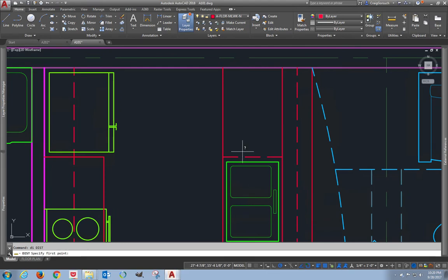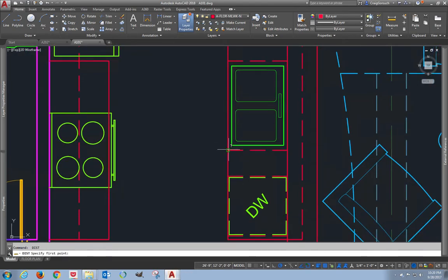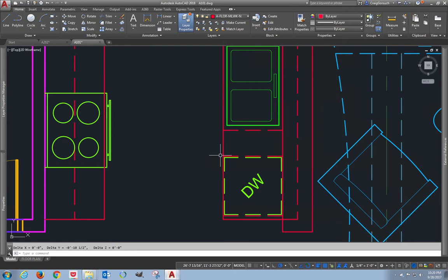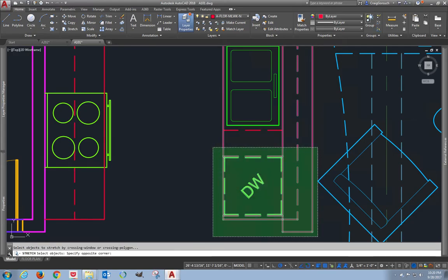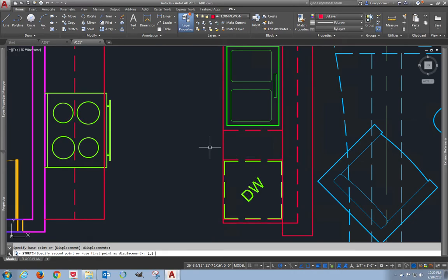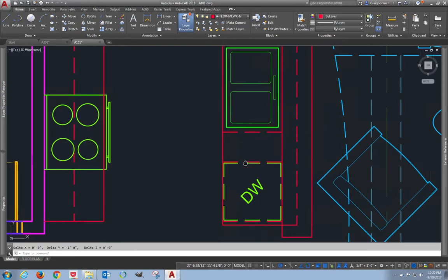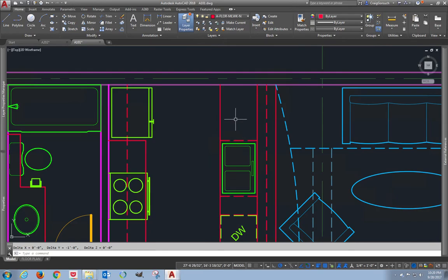That tells me that down here at the end, I have an even 3 foot. That's happy. And what about this? That's only 10 and a half inches. So there's where that 1.5 inch went. I'm going to use my stretch command, grab a hold of this, and stretch it down 1.5 so that my cabinet here is 12 inches. Now, if the bottom is 12 and this top one is 3 feet, I want to move this 12 inches that way so that it's centered.